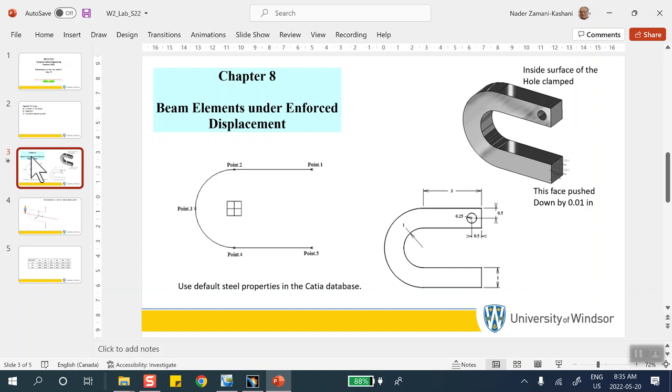Okay? And they get these stresses which are totally garbage, the deflections that are maybe garbage. So the frame analysis for rigidity and for deflection and things like that should not be done with solid elements. It can be done with beam elements. Okay. Now, if you want specific information at the joint where these things are welded together, what people do is it doesn't happen at that level. But what they do is they do a frame analysis with beams. They recover the forces, and then they take that piece where the pieces are welded together, and apply those forces that come from a beam analysis to that location and model with solid elements, etc.